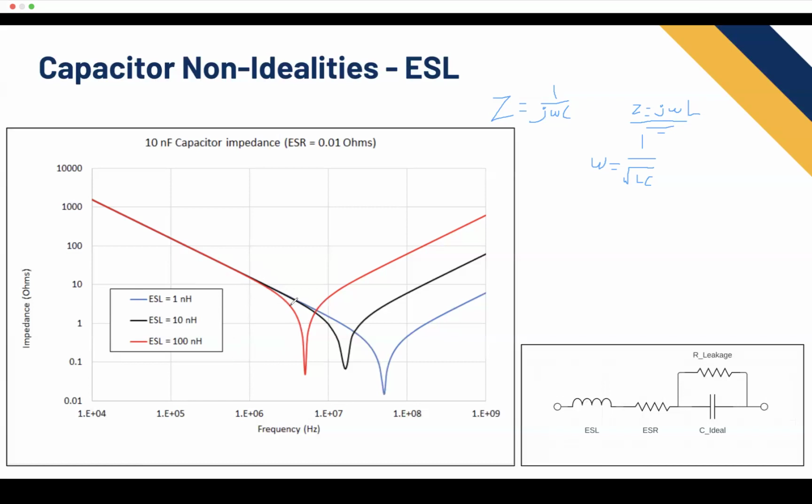Then as you get higher and higher, these terms start becoming similar in size. And then after your resonant point, the impedance of the capacitor is so small that it's really the term of the inductor that's taking over. So what does this mean?